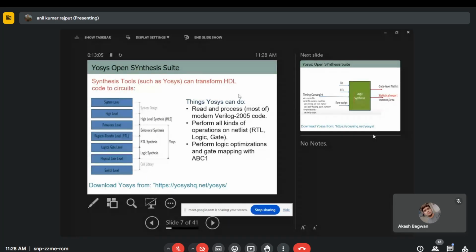And during logic synthesis, what they do is use the cells available in the technology library, such as NOR gate, NAND gate, inverter, XOR gate, and D flip-flop, or OA gates and AO gates, to develop the logic synthesis. After that, they basically generate a gate-level netlist. And these different gates are used to design your behavioral codes.